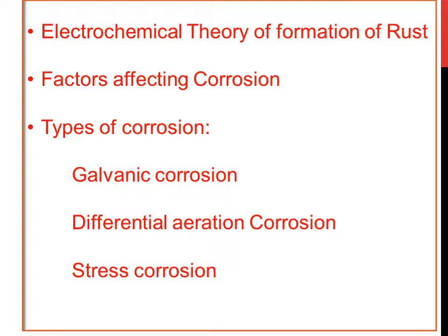And we also discussed pitting corrosion. It is a kind of localized corrosion where you have uneven distribution of air or oxygen due to dust, a water drop, sand or any chemical on the metal surface, confined to a small area.